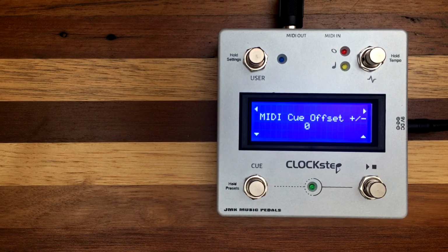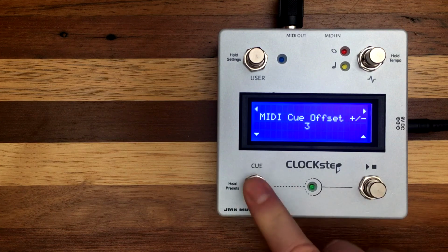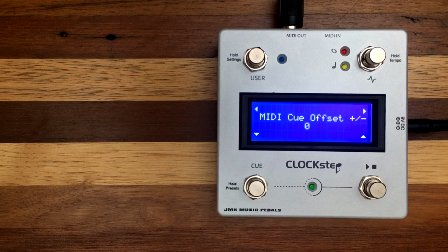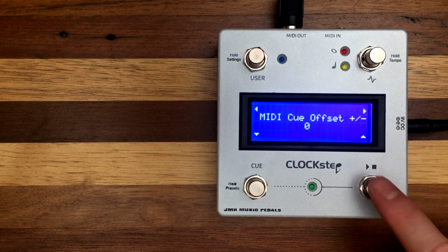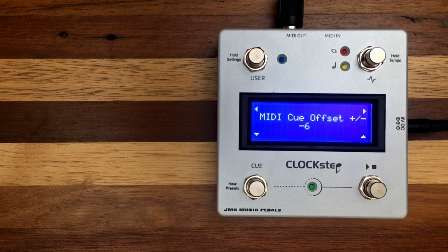Consider for a second the fact that MIDI is a serial messaging protocol. MIDI messages are sent one at a time, and no two messages can arrive at the exact same time. The implication of this is that although CLOCKstep can queue an action for the first beat of a bar, the command itself cannot be transmitted along with the actual clock message and executed at the exact same time on the receiving end. One exception to this is the start command due to how the MIDI spec is written, but the execution of all other commands will be up to the receiving device ultimately.